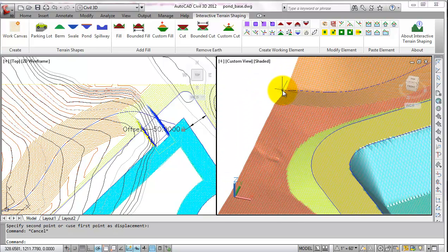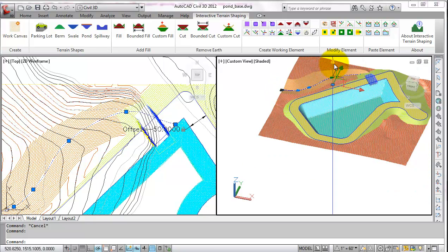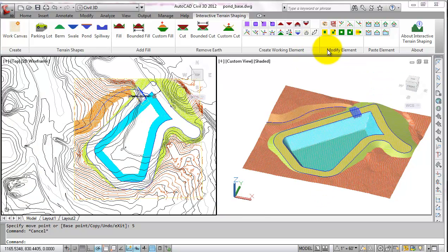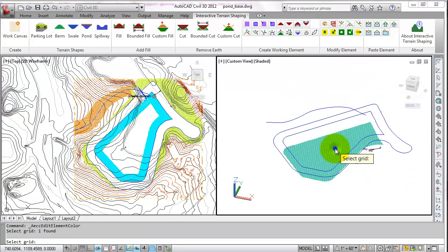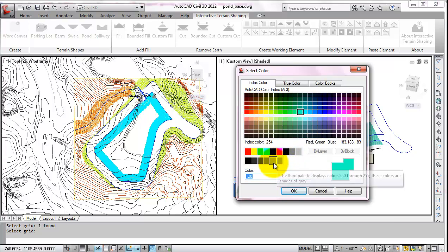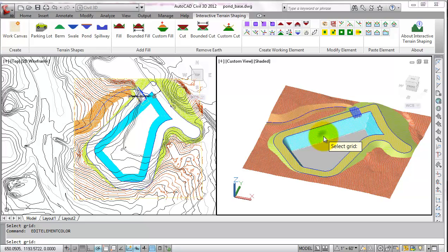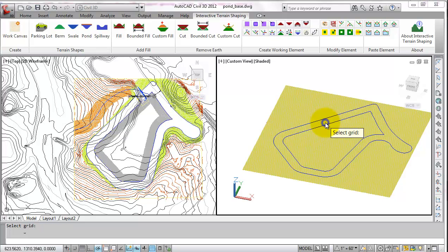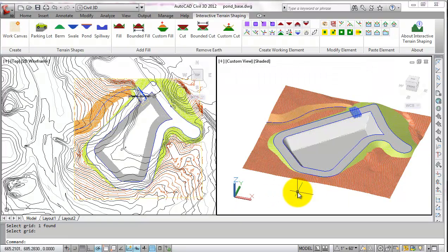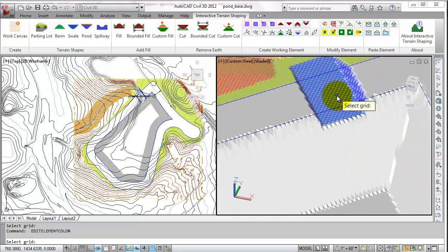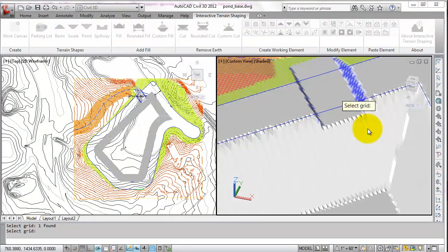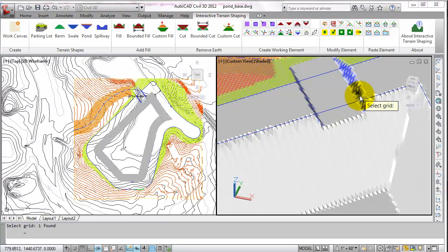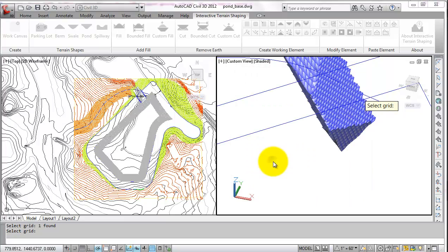To direct the runoff downstream of spillway, I can adjust the dimensions of the outfall channel in Canvas by editing the baseline in 3D. And if I'm not satisfied with the default colors, I can change the colors of any piece and make them look real. And if you view the model closely, you can see some ragged edges. This is the artifact of grid model, and these ragged edges will disappear once I convert the model to the solid view, and I'm going to show that soon.